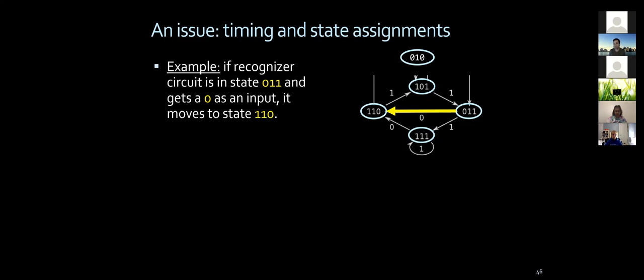So you can build an asynchronous circuit to do this type of computation, and that's not going to hurt you. Unfortunately, there are a lot of cases where you need certain synchronization. The algorithms are built this way, right? So here, it's no different. And we're going to see where these problems arise very carefully here. So assume we have this state machine here, right, that has 0, 1 state. It has all these other states.